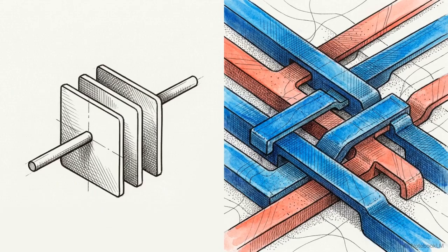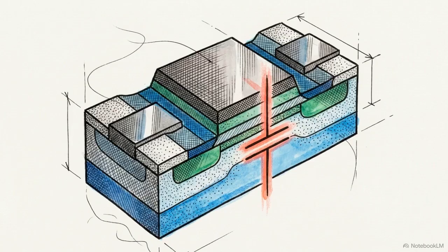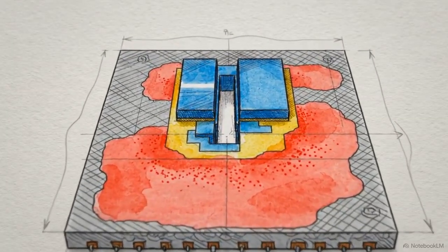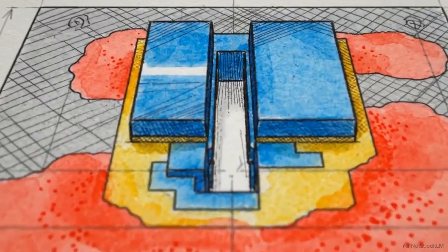While schematics represent this load as a discrete capacitor, modern integrated circuits rarely contain such components between logic gates. This symbol is a mathematical simplification of several parasitic physical phenomena that appear whenever transistors are interconnected. These complex parasitic values are embedded deep within the physical architecture of the downstream MOSFET being driven by the inverter.